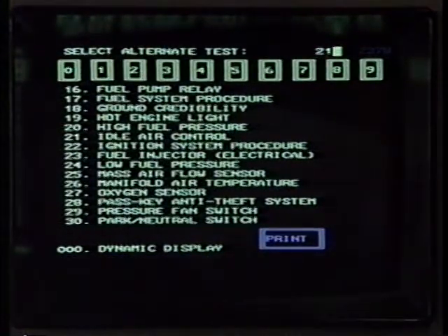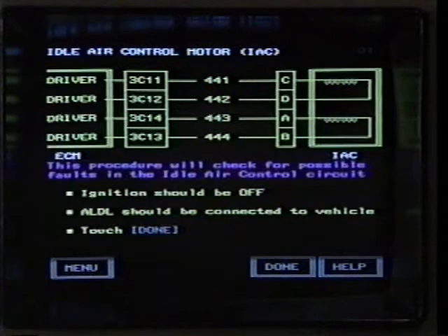For example, it would take a technician at least 40 minutes to perform these IAC valve checks. The IAC FIP uses the speed of the computer to check the wiring harness, the motor, and the signal from the ECM, and it only takes a few minutes.